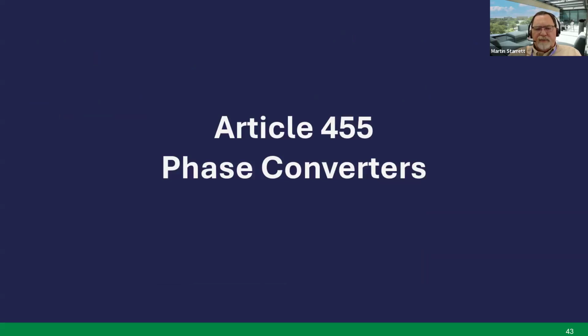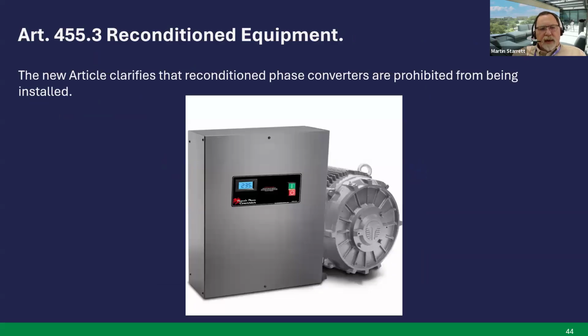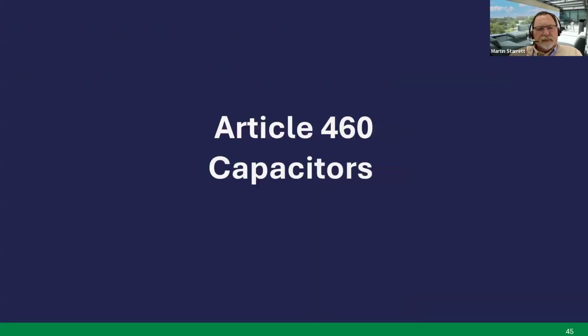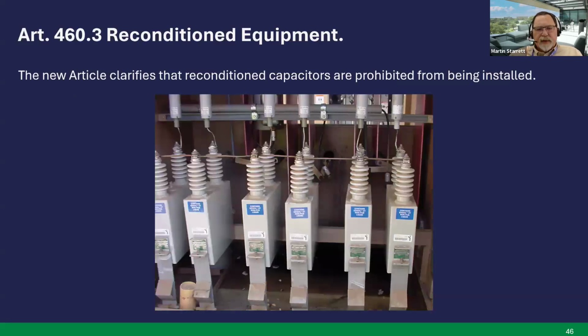Article 455 phase converters. Next slide. Another reconditioned equipment article that clarifies that reconditioned phase converters are prohibited from being installed. 460 capacitors, similar. Article 460.3, you're not allowed to use reconditioned capacitors.